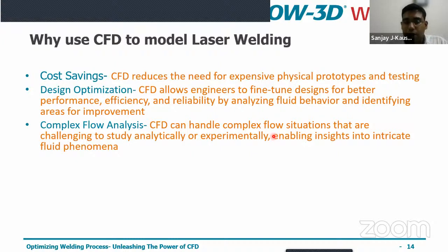So why this is forming is mainly because of the melt pool dynamics that are taking place. It is very difficult on the shop floor to track this melt pool dynamics as it goes on, because the melt pool takes place at a micro level scale. It's very difficult, or I would say even impossible, to track how the melt pool is acting on the shop floor. But a CFD software helps you do that in the simulation, in the computer itself, and you can see at micro level what is happening. How is the splatter happening? How is your melt pool dynamics forming and things like that.